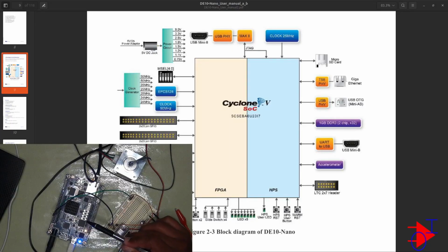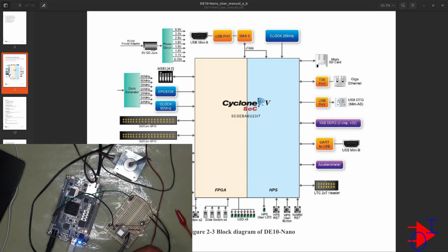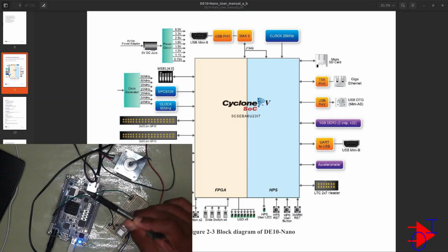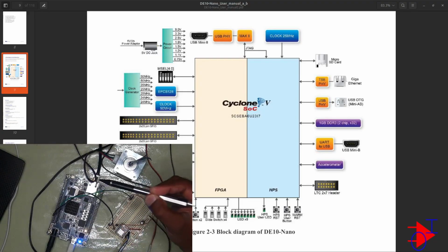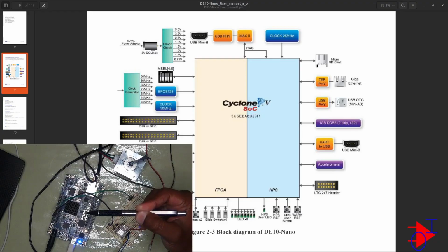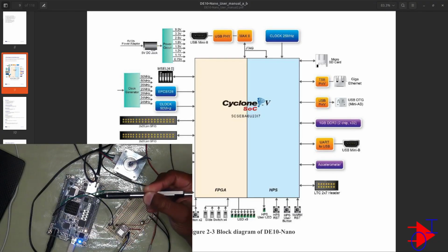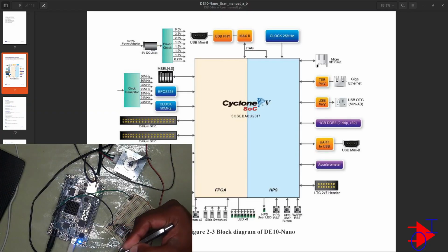What I want to do is basically turn this into my motor driver, and it's going to control three different motors: right ascension, declination, and the focus. And for each one, by name, I want to control its speed, its position, its direction, etc. So with those objectives in mind, I want to have a good handle from the HPS to receive commands and process those commands, and then at the end put out instructions for my FPGA, which the FPGA can take and execute. That's basically the whole plan.